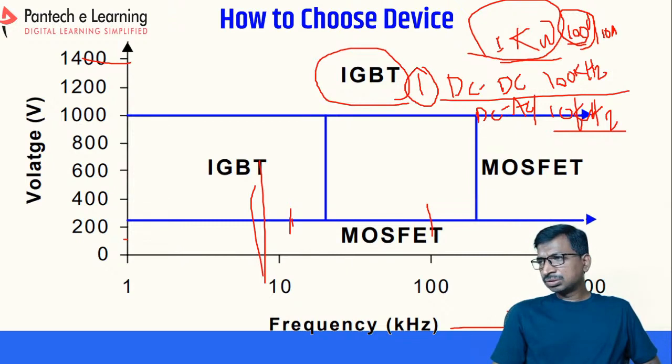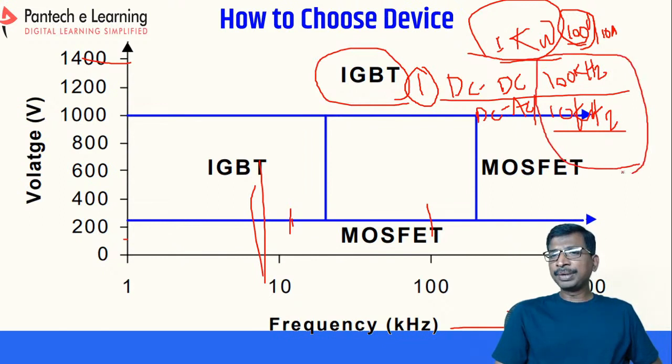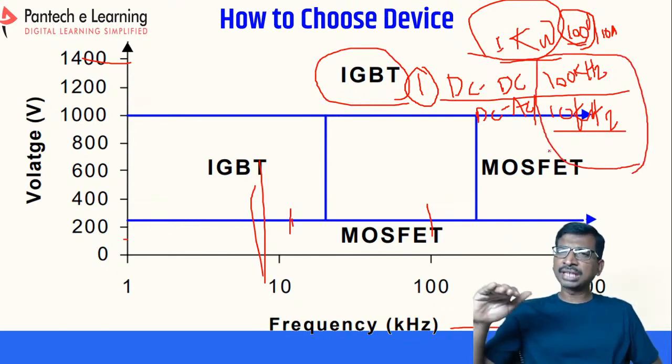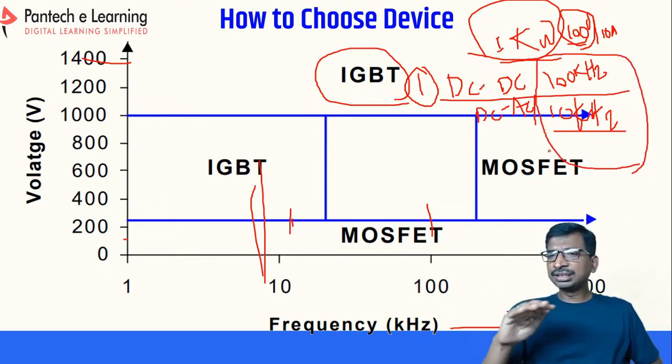With the switching frequency, you can change the speed of the DC motor. For a 200 voltage LED driver, here you have to understand the switching frequency. Always you should identify the switching frequency. For DC to DC applications, keep the switching frequency high, whereas for DC to AC applications, switching frequency must be less than 10 kilohertz or 20 kilohertz.